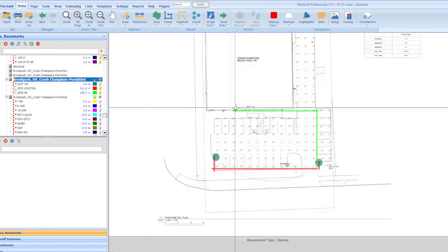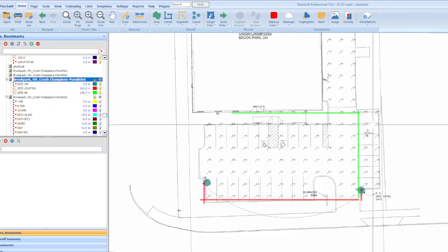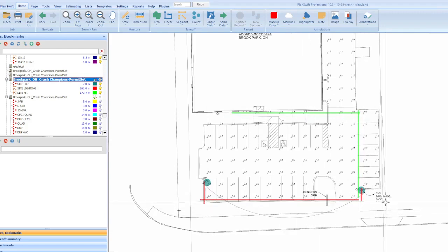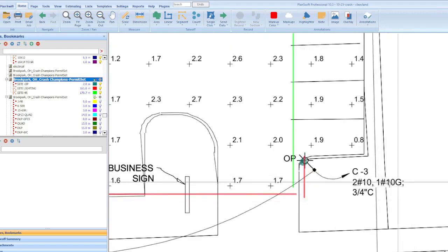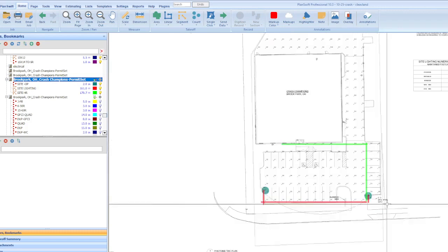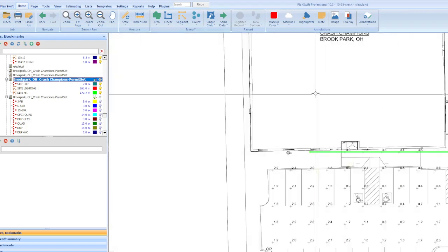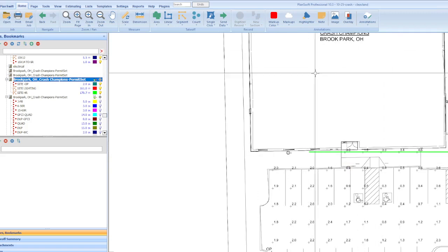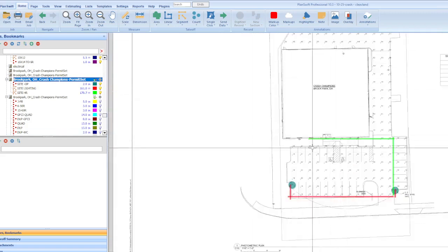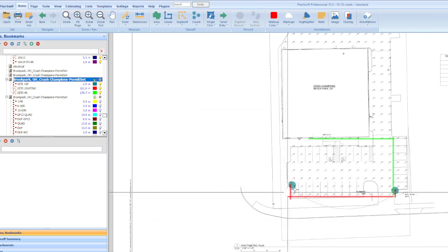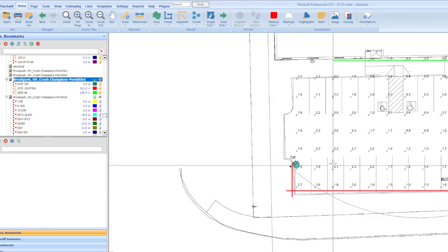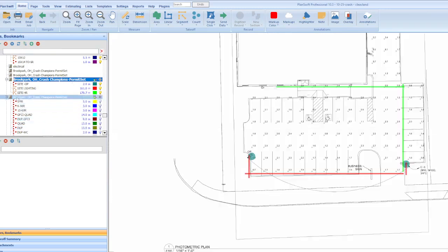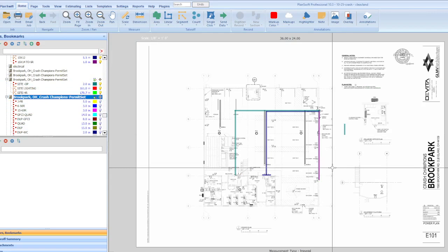Okay? In terms of, so we know this is underground. We know that's PVC because it's site, right? So we don't have to think twice about that. And we know that it's 3 number 10s and a 3/4 inch PVC. Home run 2, position number 3 in panel C. So the panels where I took it from here, and then once I get into the building, I add whatever additional wherever the panel is in the building. And you got to account for it coming up, right? PVC, to EMT, or rigid, or whatever. So just add like 10%, nothing that's mind-boggling. Especially for initial estimate, because you want to bid as much as you can now.